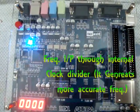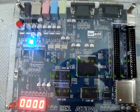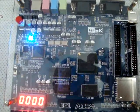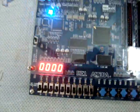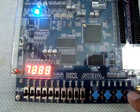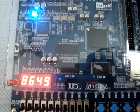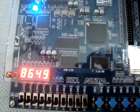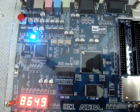Before actually measuring the frequency from an external board like a frequency generator, I have generated a frequency internally in the FPGA. I generated 8651 Hz, that is 8.6 kHz, using a clock divider. Now let's check whether it measures it accurately or not. So it is quite precise, it is measuring 8.649 kHz, and that's good, it is working well.